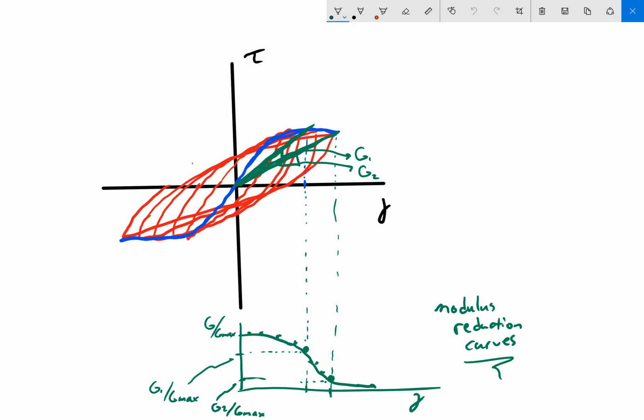And what I mean by this, let me pull up a little whiteboard here to show you. So if I have the ground surface and I have some soil layer down here of interest where I have the center point of that sublayer, and I'm interested in computing what the settlement in that soil layer is going to be.